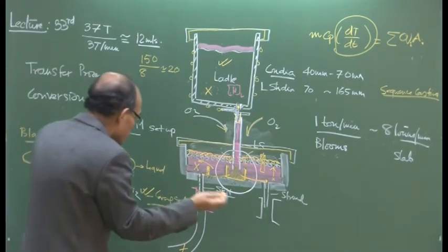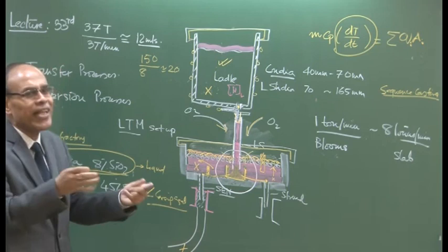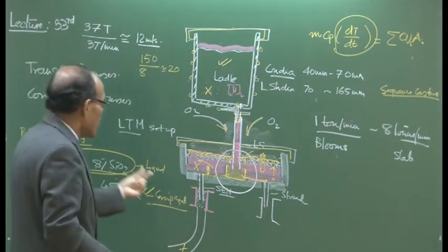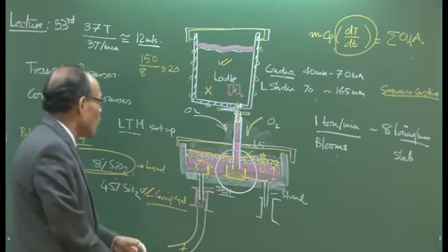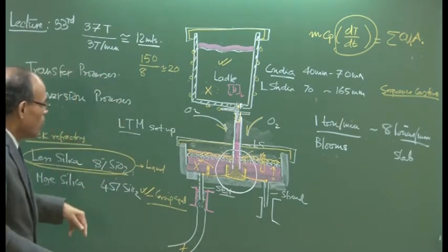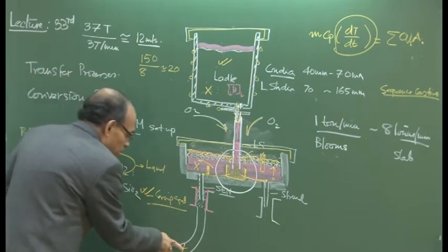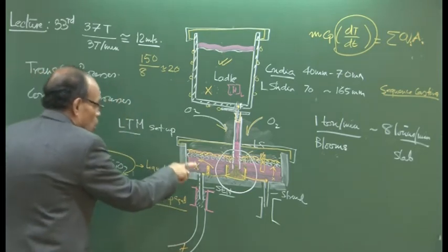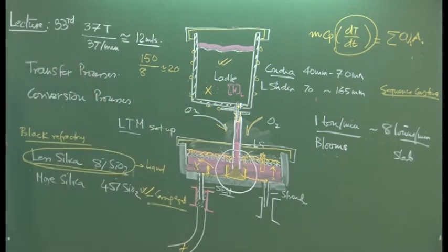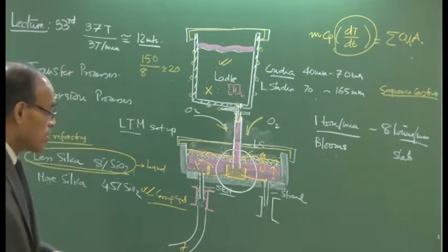It may contain the starting of the casting. The beginning is not a steady state, so it is not a smooth condition. So the first slab or bloom produced may not be of correct quality. So, second bloom onwards, if you analyze and find that the dissolved aluminum content at steady state and the dissolved aluminum in the tundish are essentially the same, then we can say that there is no reoxidation which has taken place in tundish.